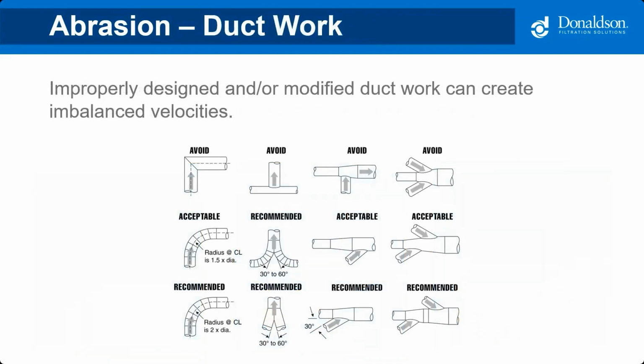And then also ductwork. I'm not going to go through this one by one, but just avoid 90-degree turns, and avoid bringing in ductwork at a bad angle. A lot of this stuff happens when you put a new grinder on and you're just like, just run it over and stick it in that ductwork. What can happen with a lot of these bad ductwork designs is you're going to wear out those corners on the ductwork, and then you're also going to add a lot of static pressure to the system.